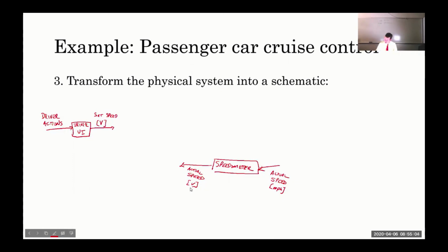So now we've got two speeds measured in volts that we can take the difference between and do operations on that. Now here's where, this is actually where we're gonna start talking about electrical engineering. You could use any number of different circuits to do the following operation. You could use a diff amp. You could use a Darlington pair. You could use what I'm going to employ, which is going to be just a plain old op amp. I'm going to introduce an impedance network here. What is going to go into that impedance network, we don't quite know yet.